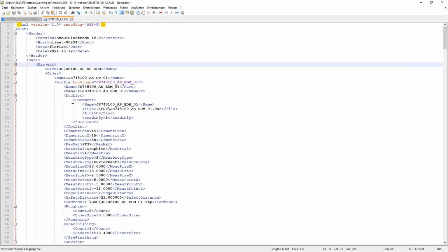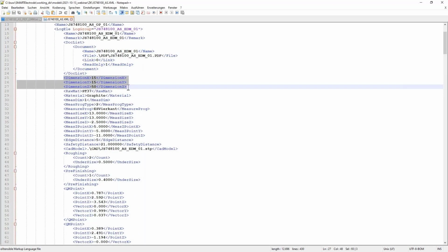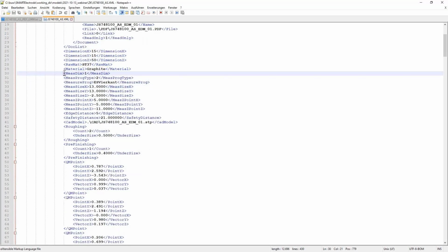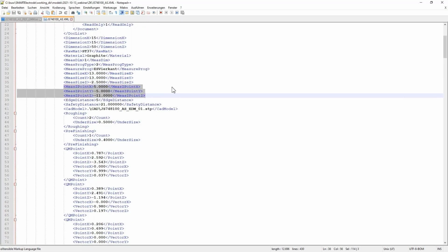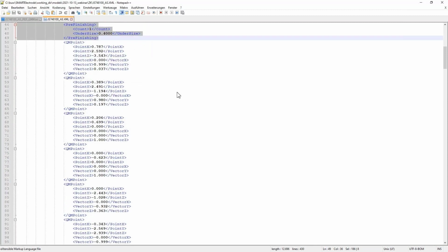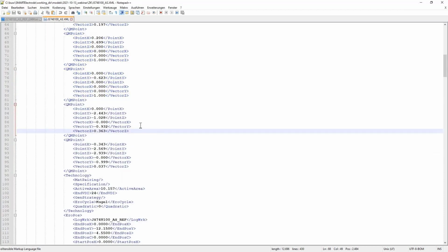The content of the XML, so this is the link to the PDF file. We can add the blank size. We have the workpiece material and the electrode material, electrode coordinate system position, type of program, type of blank, size of measuring frame in this case. And we have the updated position of our reference point for the automatic measuring. So we have some technology data. Oh, no, at first it's the link to the step file. And we have some technology data, undersize quantities. Here also listed the measuring points based on the coordinate system set in the export options.